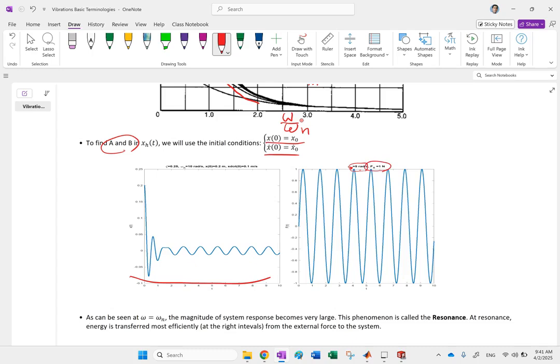In this system, my zeta is 0.25, my natural frequency is 10, and the initial conditions are 0.2 and 0.1. So if you see, the solution starts from 0.2, it has a small positive initial slope of 0.1, which is hard to see. You have to zoom into it. There is a small bump here that goes up and then starts dropping down.